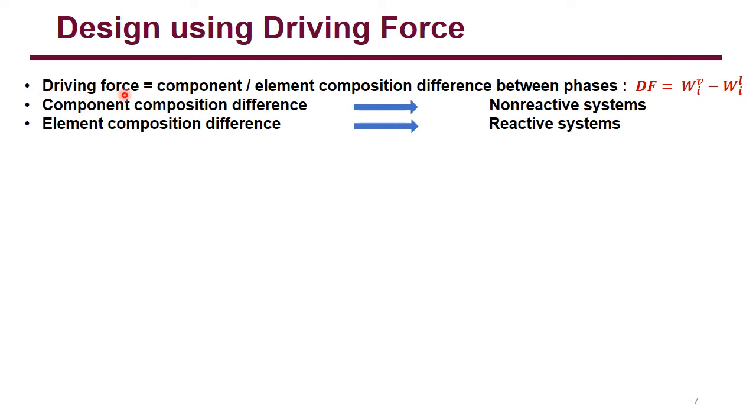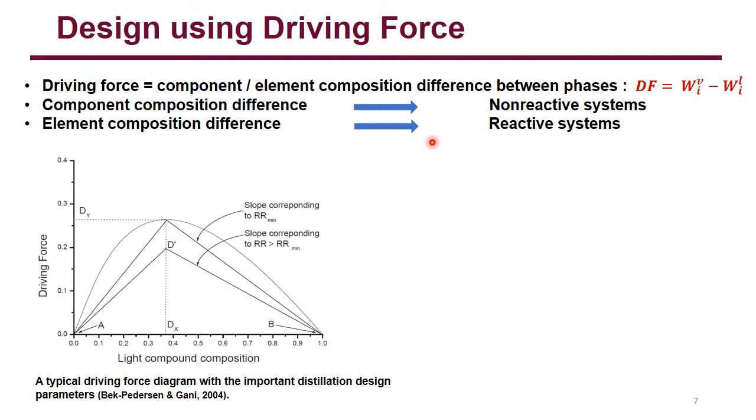If we define driving force in terms of elements, we can follow a similar procedure for the design of reactive systems. Here is a typical driving force diagram that can be used for the design of non-reactive systems. Here we can see that the driving force is generally concave upward, and there exists a point where the driving force is maximum.